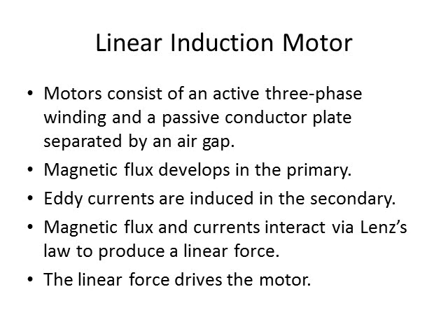Note that the eddy currents basically produce their own magnetic field, which is opposed to the original field in accordance with Lenz's law. The repulsion between the two fields provides the translational force, that is a linear force, which drives the motor. Either the primary or the secondary may move, depending on which is fixed and which is left free to move.